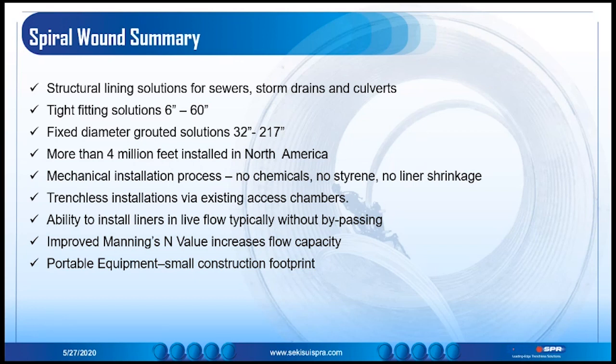Thank you, Chris. And we have another one about liner bracing here. Is simple bracing used for all projects, or are there other bracing options used for projects that use structural grouts or for non-circular applications? Simple bracing is typically used for these types of applications, but additional bracing can be incorporated for specific projects and/or applications in order to prevent liner flotation. So depending on the type of grout used, we can provide the bracing options for those types of installations.